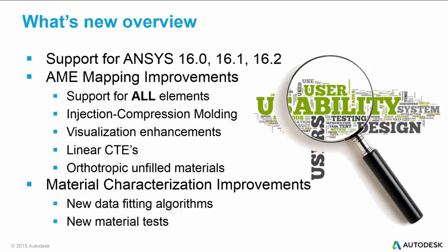We also support now linear CTEs. If you map linear data over and you only want to do a linear simulation, we'll take the CTEs too. CTE stands for coefficient of thermal expansion. And we also support orthotropic unfilled materials, talc filled, mineral filled. If it's orthotropic, we'll support it. Most importantly and most interestingly, we also added a lot of improvements for material characterization in the form of new data fitting algorithms, and also we have a new material test and fitting package that we offer you as a customer, which is really great. I'll talk about that right at the end of the presentation.